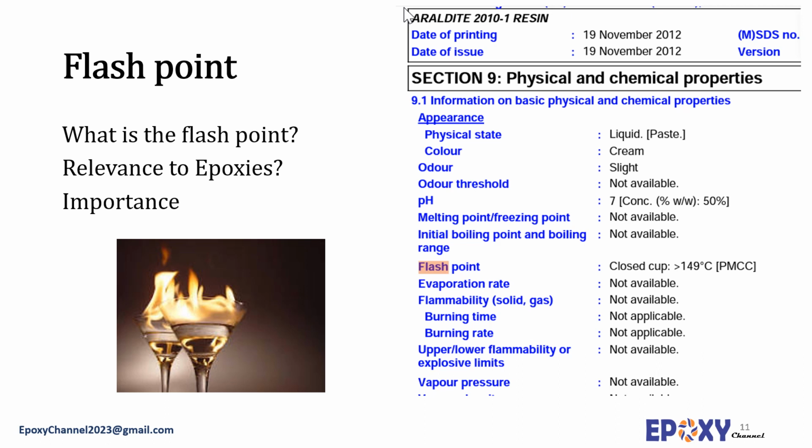However, a high flashpoint indicates you have a lower fire hazard when exposed to high temperature heat sources. When operating equipment is at high temperature, a high flashpoint is important first and foremost for operator safety. The flashpoint of the material is one of the required elements on the safety data sheets. Assuming you have a GHS compliant sheet, the flashpoints will be listed in Section 9, Physical and Chemical Properties.